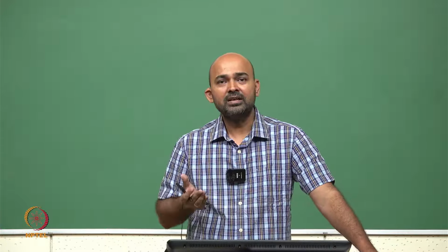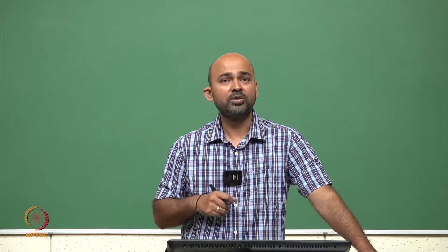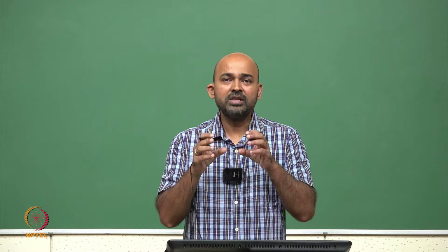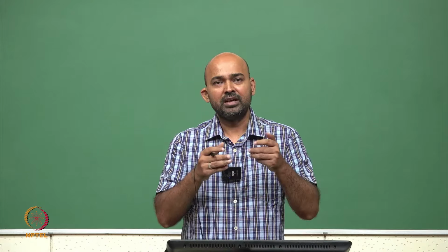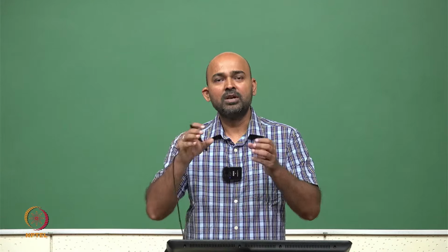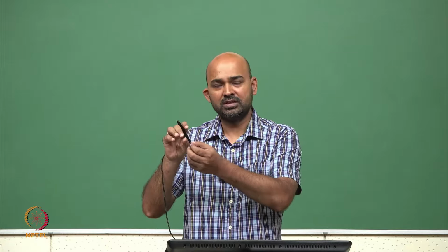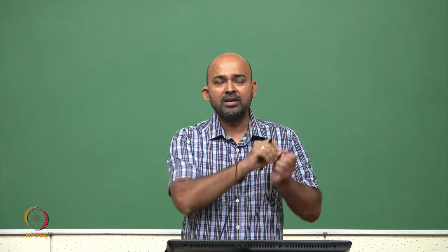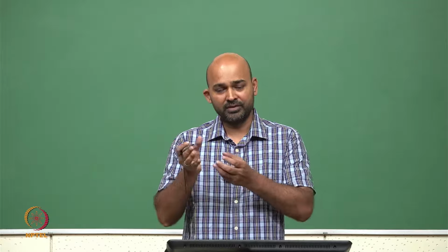However, the second type of gates we have are sequential logic gates, which we are going to discuss today. Now, in the logic network we have, some of the inputs are there and based on that we have an output, but some of the outputs of this logic circuit are fed back to the input of the same circuit. So, for example, we have a feedback network in this, very much like a control system.